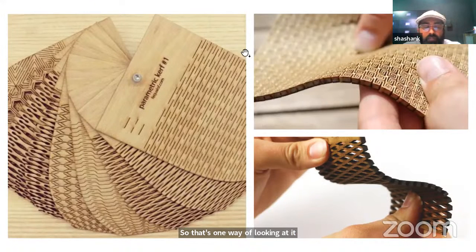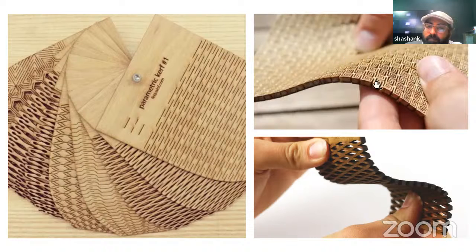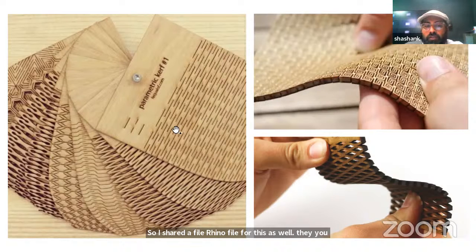Now, apart from the locking mechanism, there's something known as kerfing, where you can take 2 mm or 3 mm of wood, or actually more than that if you want, depending on the cuts that you make. Different designs are also available. You can bend that material just by basic cuts. I'll share a Rhino file for this as well, which you should try out. Till the time you don't try these patterns, you won't really understand.